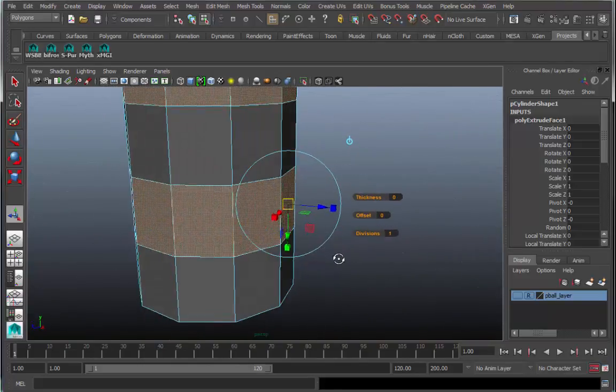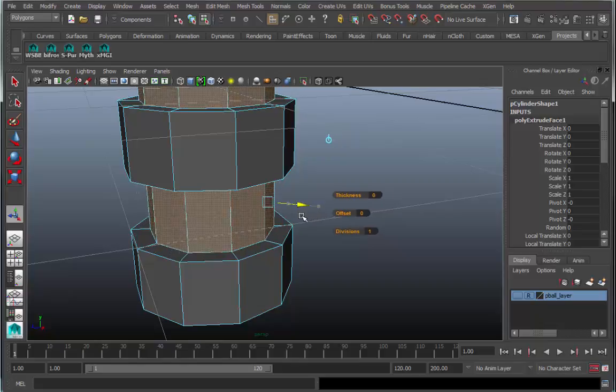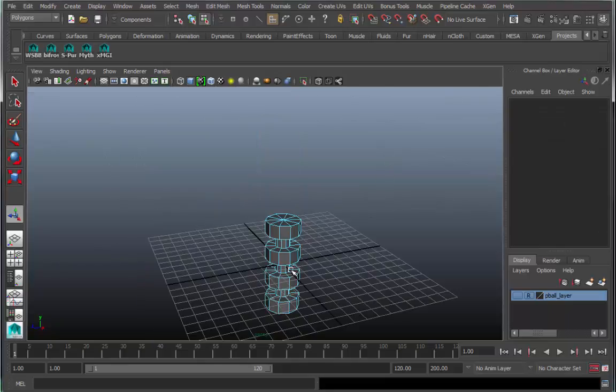And it's very important because you need to identify which way is out from that one control. Why? Because when we move it, it will move each and every one of these selected polygons in a relative fashion, not an absolute fashion, which is what we've been doing thus far. So if I grab the tip of this arrow, this blue arrow, and push it in, watch what happens. All of them get pushed in according to their normal. And so I've quickly made a nice little lightning rod.